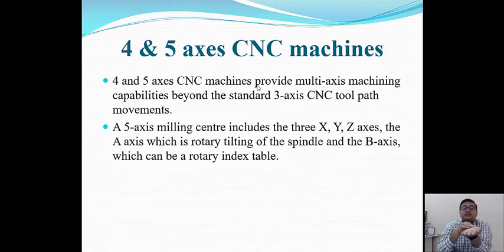This particular magnetic chuck can also rotate the tool as well. So if the tool can be rotated clockwise and anti-clockwise, or in the Z direction, then we can have more axes. If the workpiece can be moved clockwise or anti-clockwise, then it could be considered as 1 axis. And again, if the rotation of the workpiece can be in the Z direction of the workpiece, then it could be considered as another 1 axis. In that manner, the 5 axes are governed.